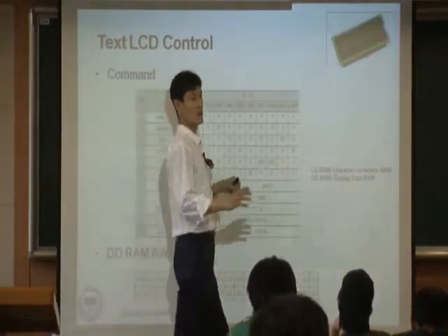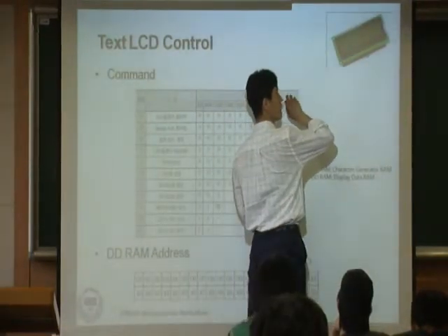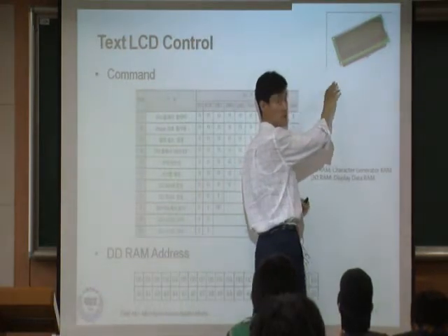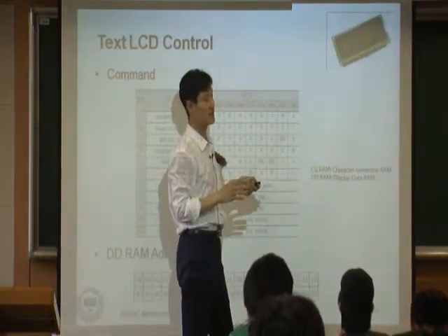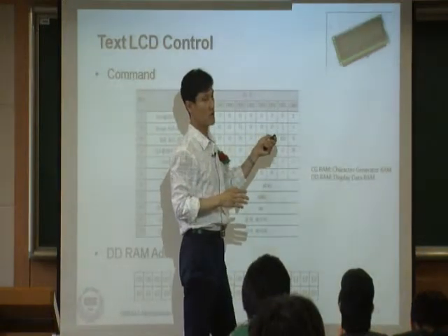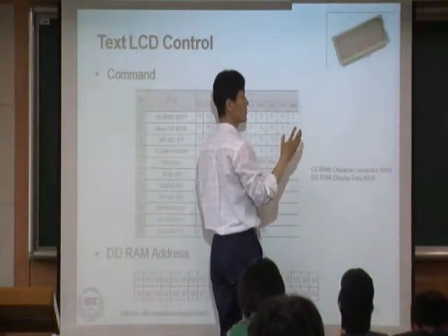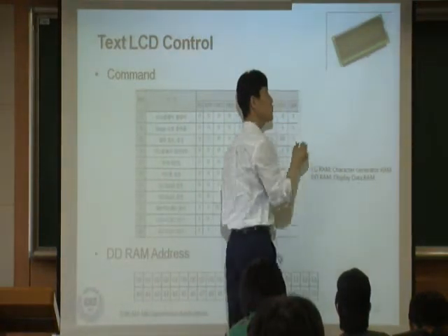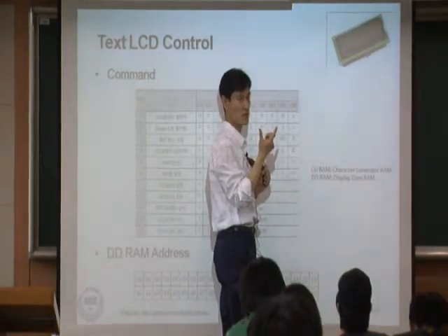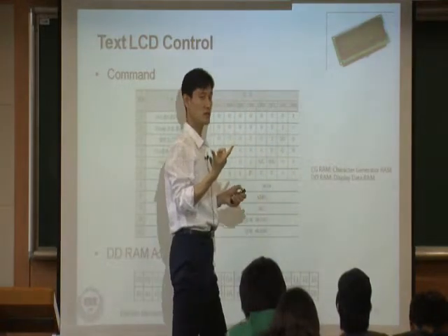This thing basically means the delay, because in the LCD device, especially for this kind of thing, you cannot write the value at a very fast pace. This LCD is very slow. I mean, every LCD is very slow. So because of that, you are going to send some letter, and you need to wait a certain period. And how much do you need to wait?